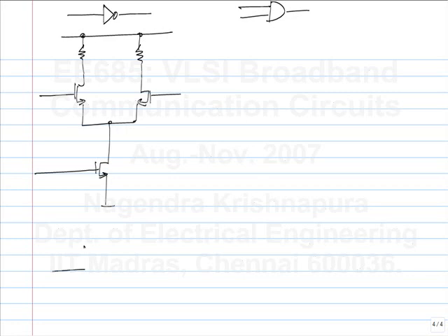So you start with an inverter. Okay. How do I turn this into an AND gate? Let me, for simplicity, take a NAND gate because that's simpler. How do I make this into a NAND? I'll have series NMOS and parallel PMOS. Okay. So can we do similar things here? There is no PMOS. What do we do?